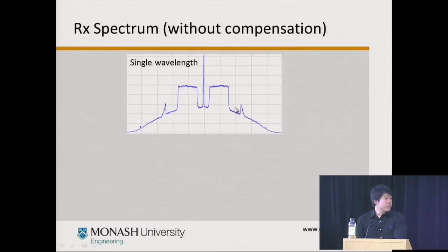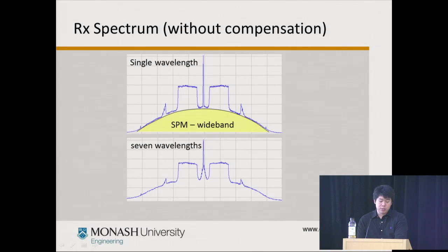However, the initial performance improvement that was achieved with this was not huge, and this was mainly due to the fact that you have this self-phase modulation effect. That's a very, very broadband effect over several gigahertz, and there's no way you can leave a gap around the pilot of that much without completely destroying your signal, or your spectral efficiency rather.